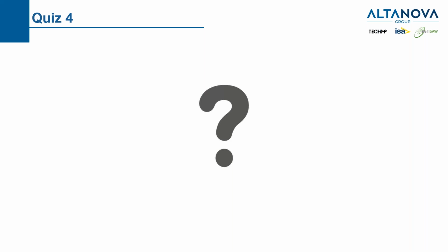If I have one PD doubling its magnitude, for me it's a clear sign of evolution. I understand this question because sometimes during the measurement we can see small fluctuation of the values around 10-15%. Such values can be considered normal due to the test. But if I see a value that is doubled in 6 months, I will take care.